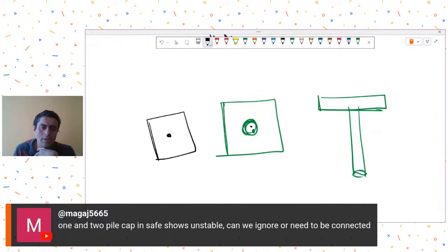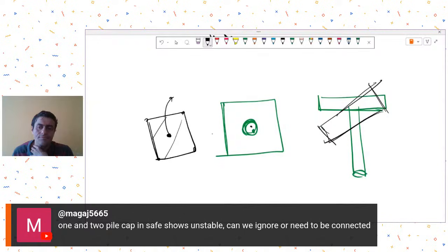Now to this point you are assigning some spring stiffness. Generally you will only give vertical stiffness to that spring. Now what happens in the case of this pile cap is that these points are all unbalanced, so to say. So any load that you apply, this thing is free to rotate, sort of. Understood? Because there is no restraint that you are providing in the SAFE model to the pile cap.